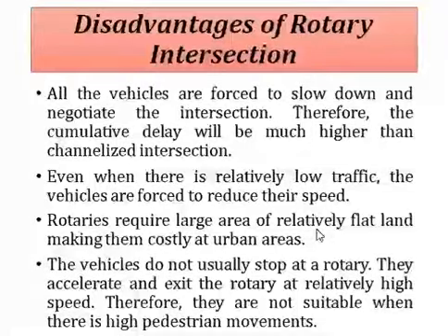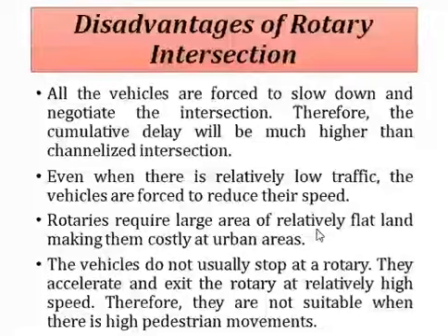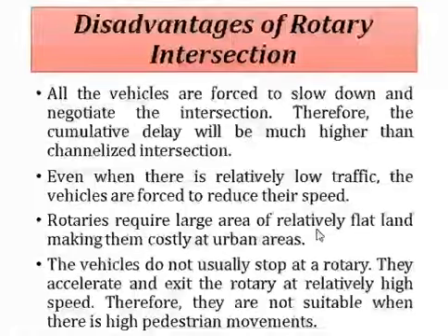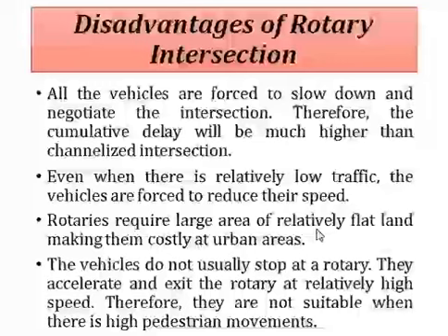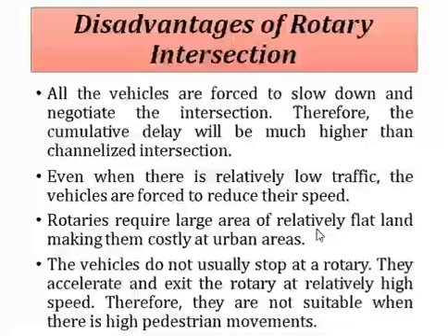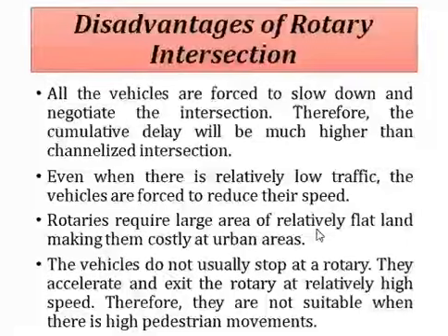There are a few disadvantages of rotary intersection as well. First one is all the vehicles are forced to slow down, so the delay at rotary intersection is comparatively high as compared to channelized intersection. Even in case of low traffic, when the traffic is very low, at night or in the afternoon, even at that time the vehicles will have to lower down the speed. The area required for a rotary intersection is comparatively very high as compared to channelized or signalized intersection.